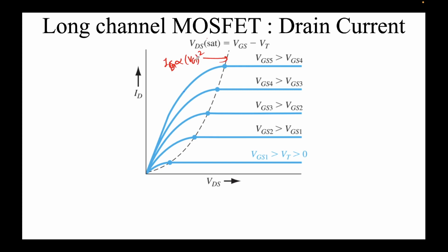I mean this is VG minus VT, but with a VG minus VT squared dependence, right? And VG less than VT is obviously not drawn here. It's a linear scale, so it's 0. All these curves are for increasing VG. So this is increasing VG.